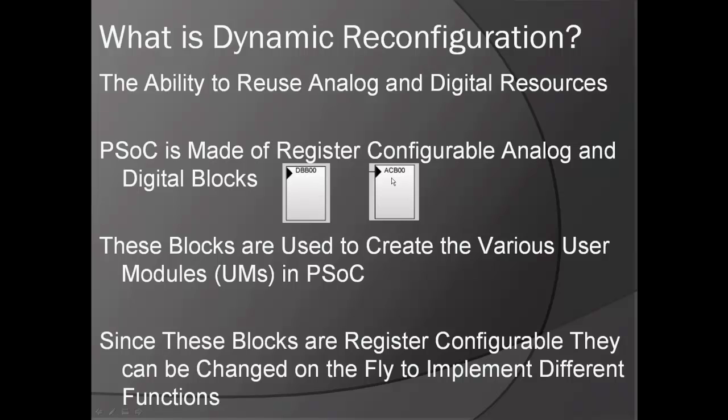These digital and analog blocks are the building blocks for Cypress user modules, such as PWMs, timers, counters, PGAs, ADCs, filters, and much more. Because these blocks are register configurable, they can be easily changed from one function, such as a PWM, to another, such as a UART, during runtime. This allows designs to implement multiple functions in the same hardware resource. This process is known as dynamic reconfiguration.